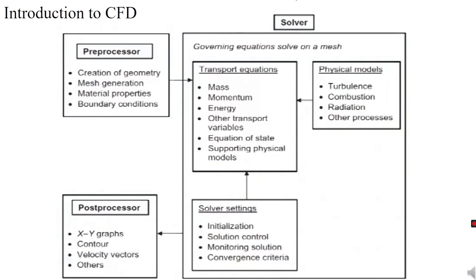Control solution monitoring with parameters like residuals for velocity, pressure and energy. Then set the convergence criteria. So residual falling below 10 to the power minus 5 is used to determine when the simulation is complete. Suppose I am having a residual value.